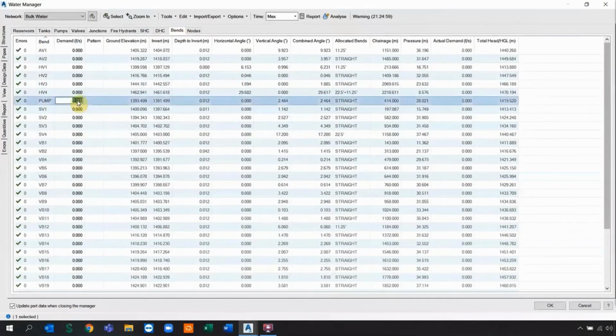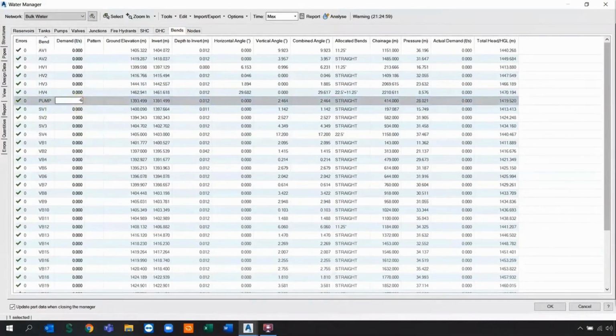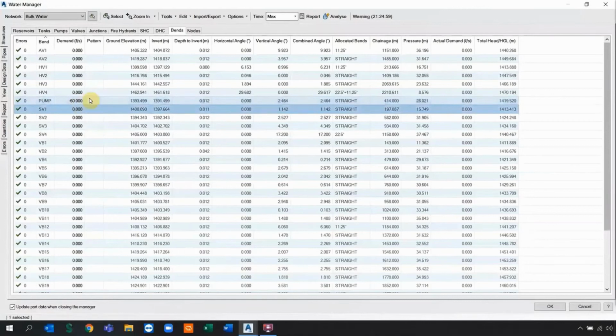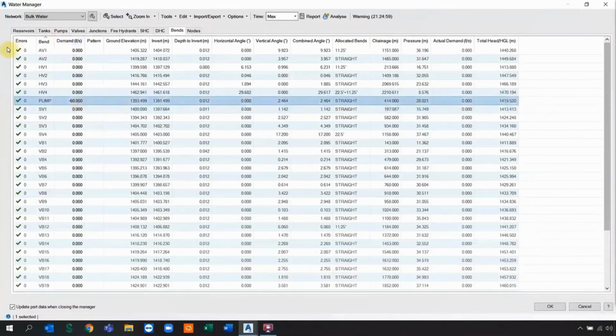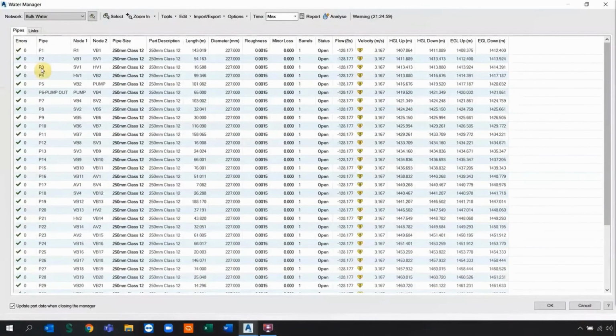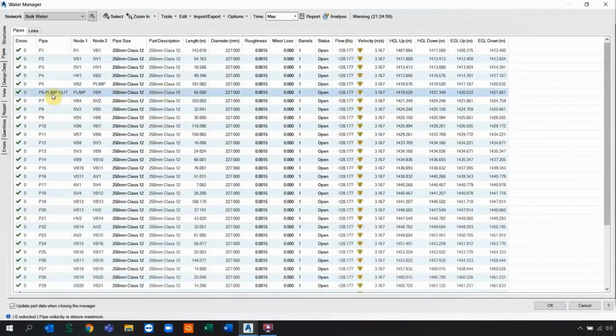So what I need to specify is just the demand. This is an estimate. You can specify any type of demand you think is required, and then we can add a certain pattern for it, because a pump system curve is normally in different segments. And then something I need to make sure of is the pipe out, which we just marked. I need to close it, because it's going to allow me to run an analysis, and it will tell me exactly what my system curve is.